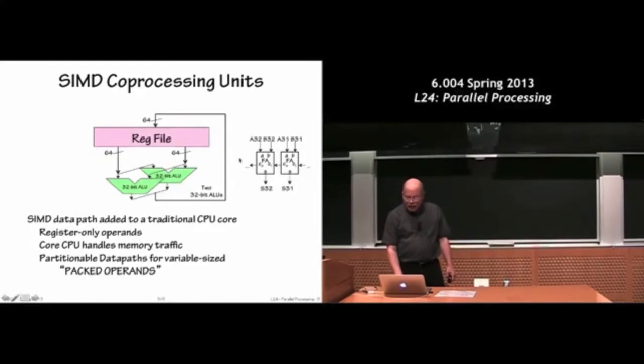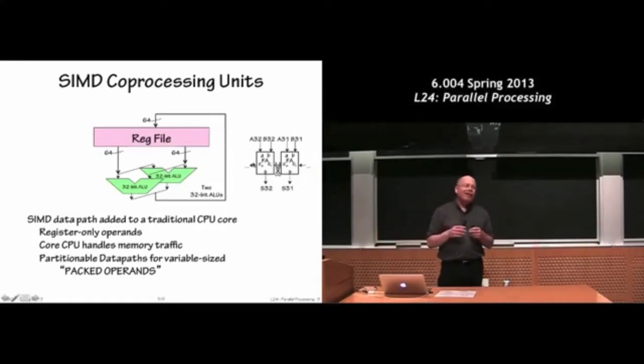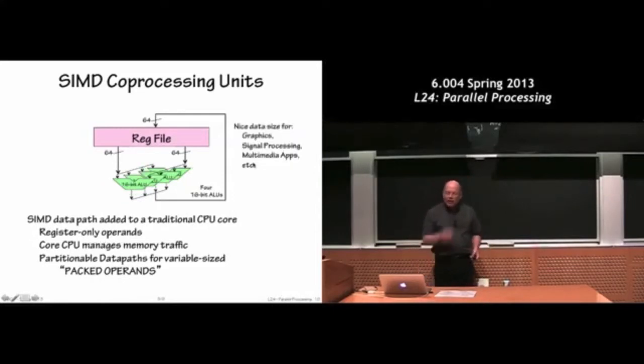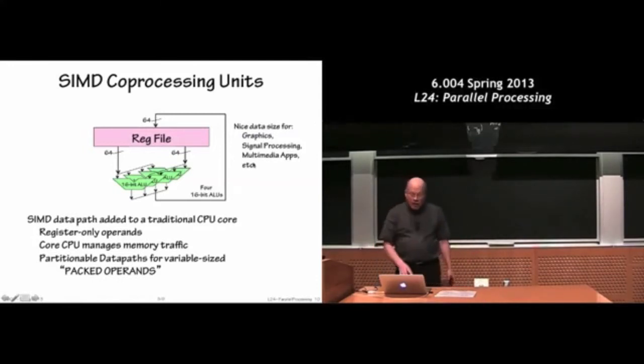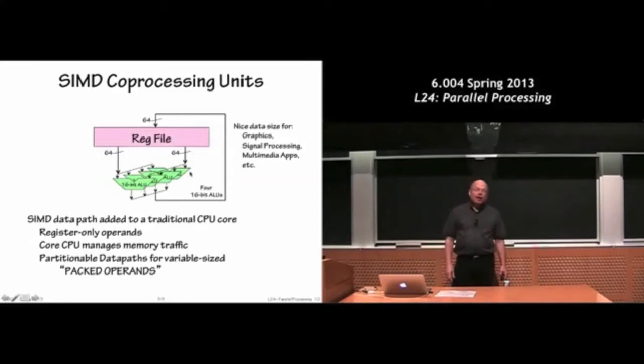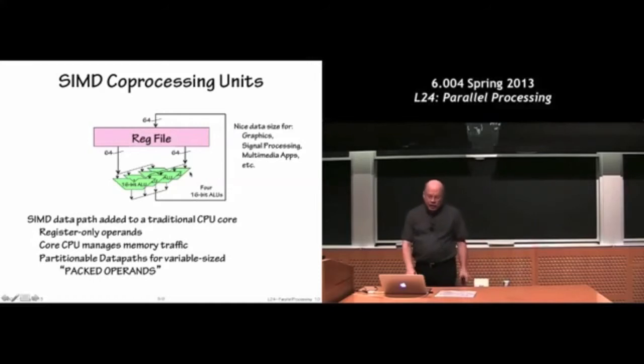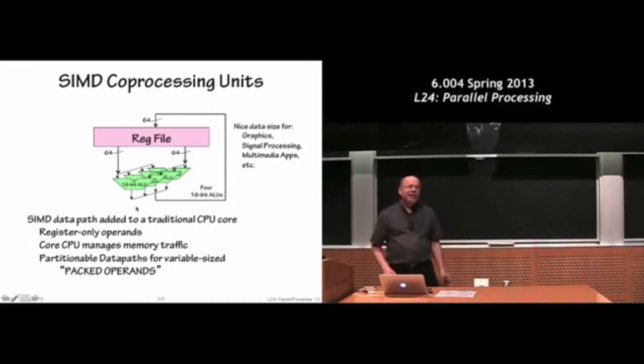Well, you just take the 64-bit ALU and you cut the carry line between the bottom half and the top half, and now you have 2 independent 32-bit ALUs. And you can keep doing that. You can turn it into 4 16-bit ALUs. So a lot of the graphics acceleration you do, or multimedia encoding and decoding for watching movies, or encoding your voice in Skype calls, whatever. Now we're working on 4 different operands in parallel. So, 4 16-bit operands. Same basic hardware, we're just fooling a little bit with the carry chains to reuse it to say, look, think of this as 4 16-bit numbers.